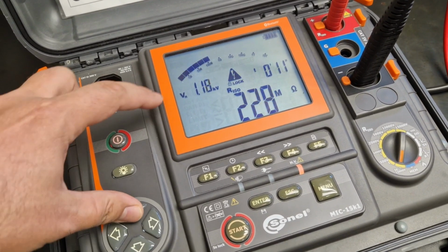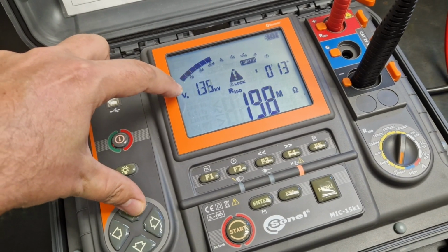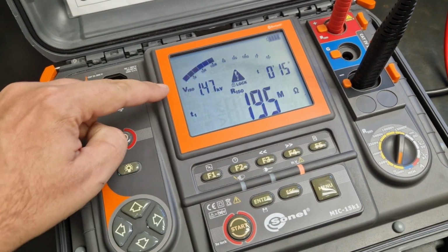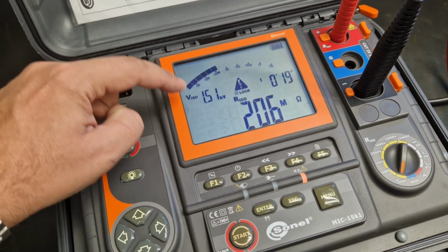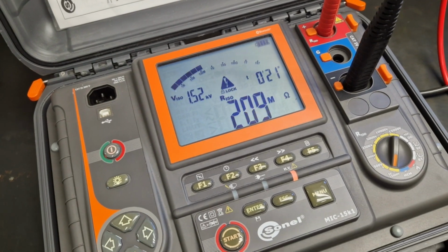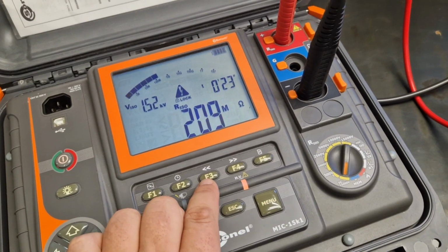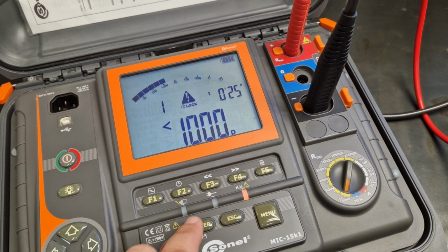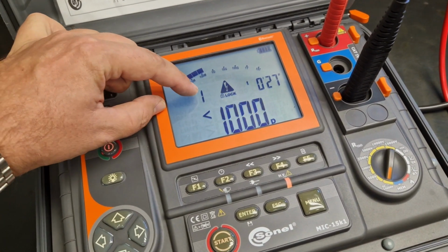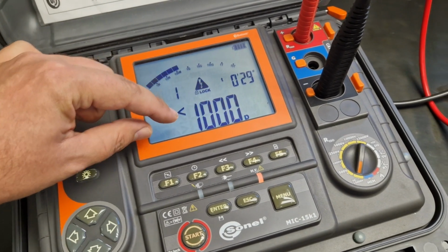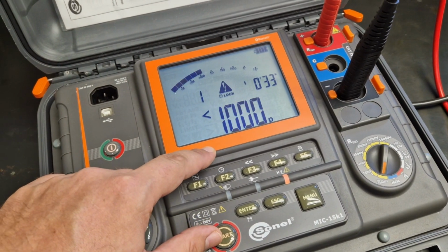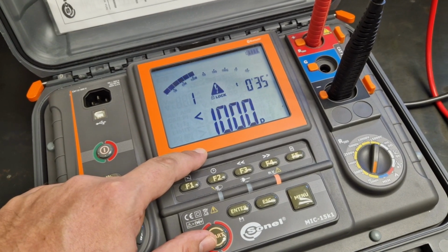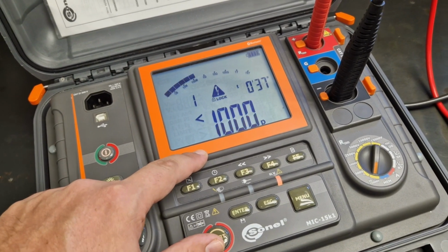So you can see that I am changing the voltage, and within a few seconds the insulation voltage will also increase to this value. By pressing the F3 and F4 buttons, we can also see the partial discharge counter, and how much charge is covered by this partial discharge.